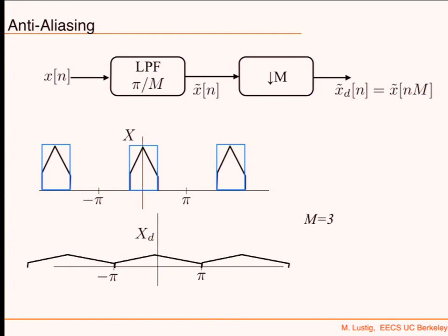You split into high frequencies and low frequencies, like in wavelets, for example, and then downsample, and you get some aliasing. But as it turns out, when you construct the signal back, that aliasing is going to cancel. We're going to talk about it later when we talk about filter banks.